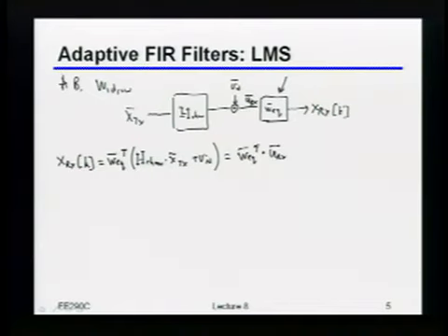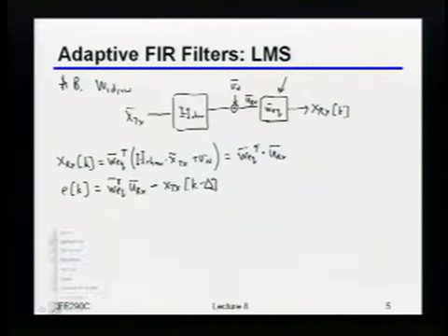But basically, if I wanted to figure out some sort of error signal at this particular sample, I could say that the error signal is essentially, after the equalizer, that's just a reminder, that's just u_rx, minus whatever I happen to transmit at some time, and actually this isn't a vector, this is now a scalar, at some time delta samples ago. Because assuming there's some delay in this channel, you just want to handle whatever that delay is. Okay? So that would be my error.